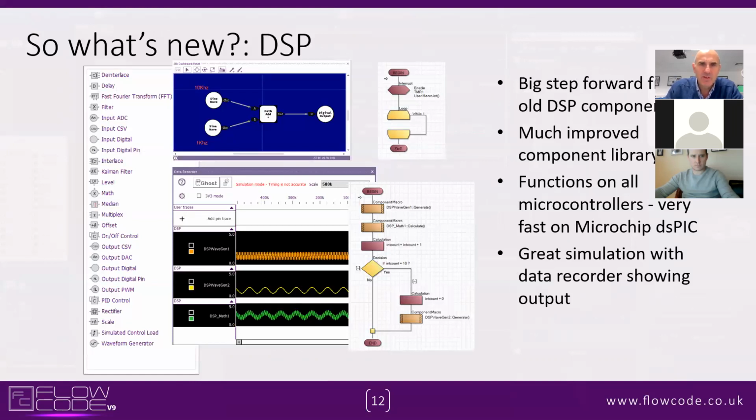ESP, this is the flow-based programming system now. Now, there are now 20 or so of these different icons that you can use, they're like components. So you drag them onto the workspace and you declare how each one connects with each other one. And what I've done here is I've just created a simple program that takes 2 sine waves and adds them and shows you the output. So the way that's done is you add 2 sine wave generators to the workspace, you add a math block and declare it as an addition, and then there's an output.